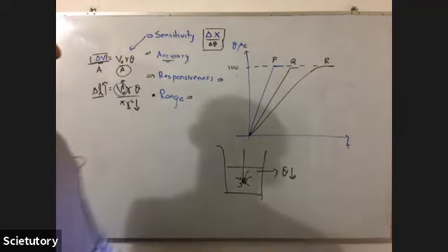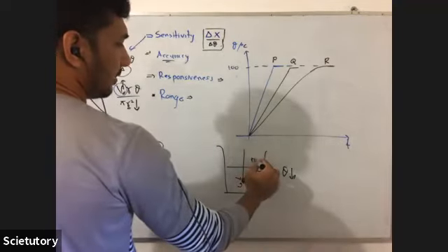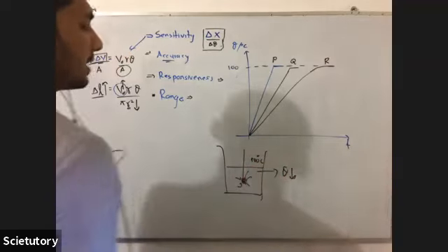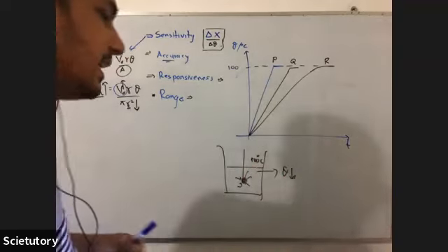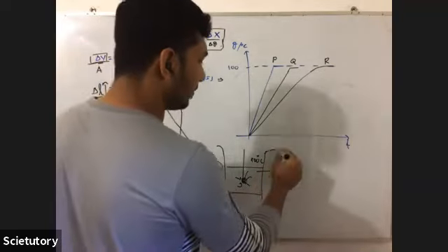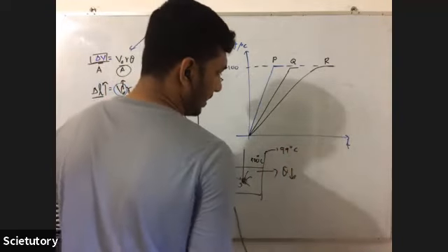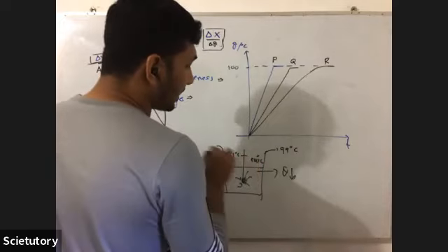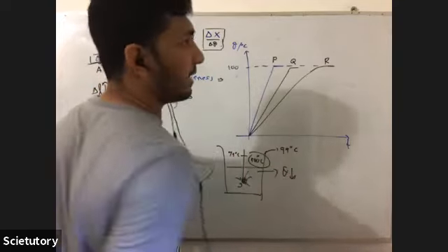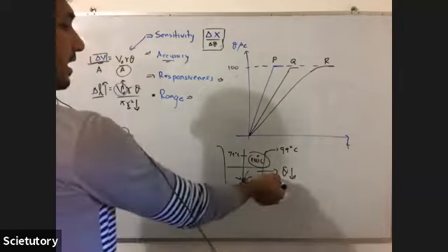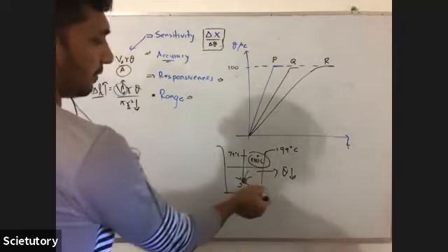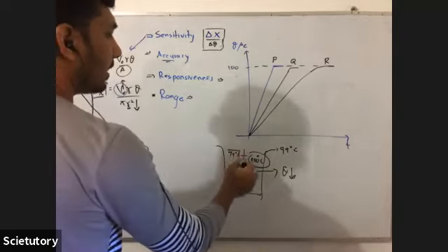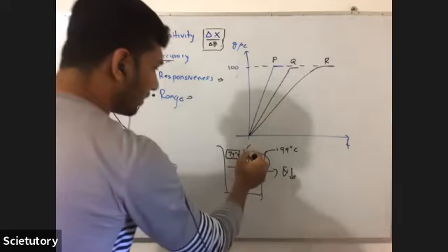So you actually kept the temperature at 100 degrees Celsius initially, but now it has fallen to 99 degrees Celsius. So what is the reading here? 99 degrees Celsius. So it's not correct. It should read 100 degrees Celsius, but as it has absorbed significant amount of heat from this liquid, now it's showing 99 degrees Celsius. So it is not accurate.